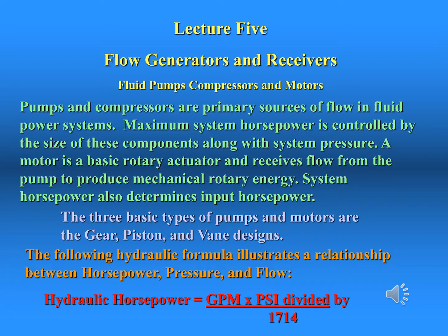No matter what design of pump or compressor is being discussed, all pumps produce flow the same way. Pumps and compressors produce flow by creating a pressure differential. Fluids always flow from a location of higher pressure to a location of lower pressure. By increasing pump volume at the inlet, the pump or compressor creates a region of decreasing inlet pressure, a vacuum, and this causes higher atmospheric pressure to push the fluid to the lower pressure location at the inlet.